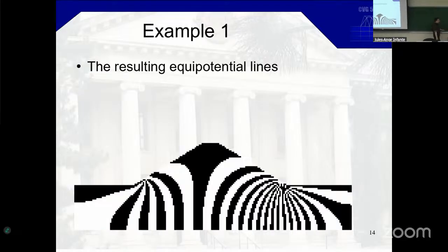And if you keep track of the elevation, right? Remember that this is your hydraulic head, right? These are jumps in your hydraulic head. This is how we generated this. But if you do your hydraulic head minus the elevation head, so you do not just subtract based on its position, you can have a column here with the Z or the elevation. You subtract the elevation from it, you get the pressure head.